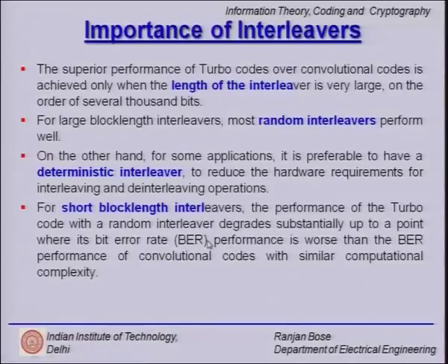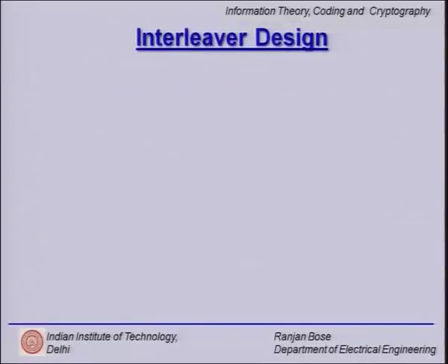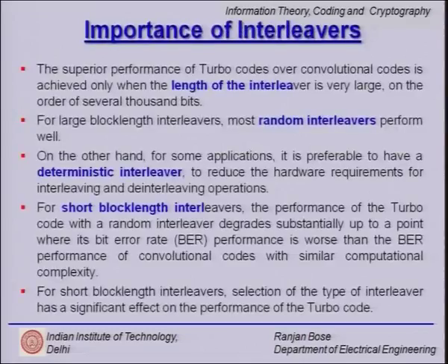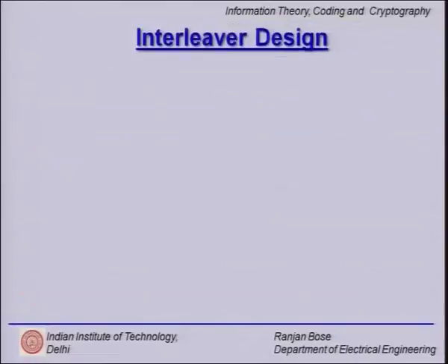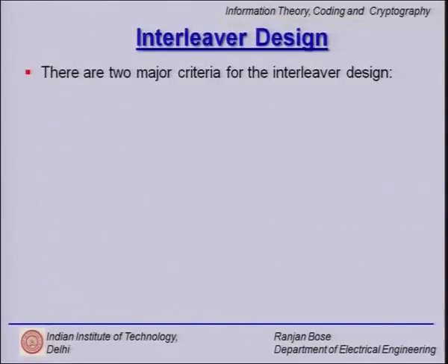Otherwise, we will go back to normal and the advantage will wear off, because you are actually puncturing and throwing out some of the bits. So, for short block length interleavers, the selection of the type of interleaver does have a significant effect on the performance. So, let us quickly spend some time on the interleaver designs.